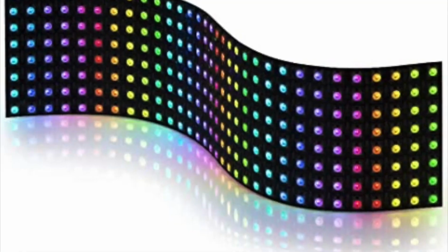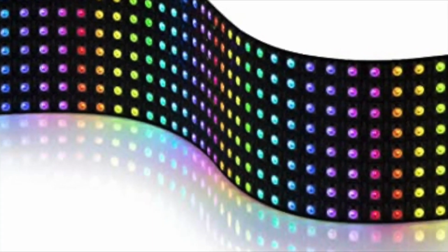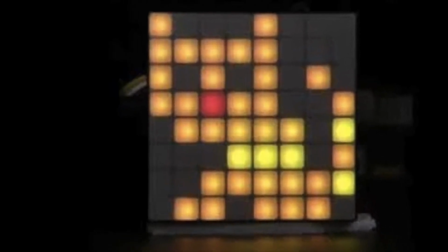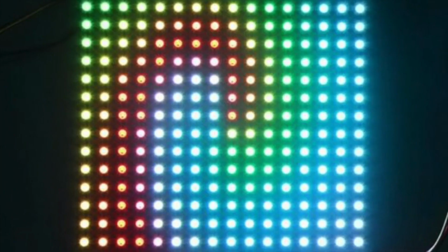LED matrices. These come in square or rectangular formats. Larger matrices require more power. The LEDs in your matrix can either be wired across like a typewriter or back and forth like a snake. FastLED can address both as long as you tell it which type you have. If your matrix doesn't say, then don't worry. Experimenting is an easy way to find out.